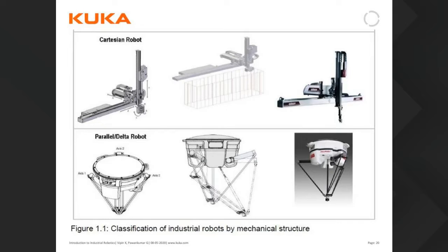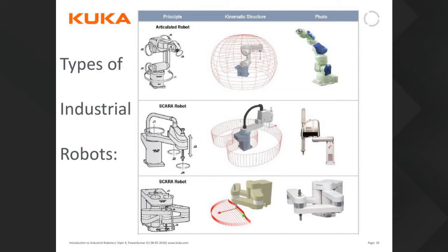Okay. So KUKA, and not only KUKA, all industrial robots mostly go towards articulated robots. Why? Because an articulated robot has 6 degrees of freedom. It means, as you can see in the workspace mentioned here, in that workspace it has 6 degrees of freedom, different orientations, XYZ positions, ABC orientations. Because of this, most industrial teams are going for articulated robot applications.